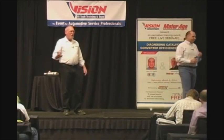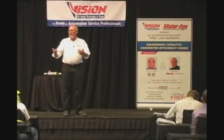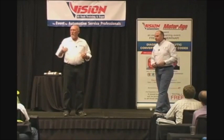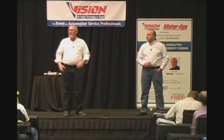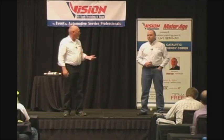The MIL light tells you something on the car has passed or failed. But if you wanted to improve your test scores, you would go back to that test. You'd like to know which specific questions you had a problem with, wouldn't you? Well, that's Mode 6. Those are all the questions the computer is asking, all the tests it's performing to decide whether that code's criteria is met or failed. And you can go into Mode 6 and see which one of those elements is not doing what it's supposed to do, the area that you need to study on. Is it something used every day? No, but it's one of those little things that you have in your back pocket. It's one more bullet in your gun belt for chasing down a diagnostic problem if you need it.